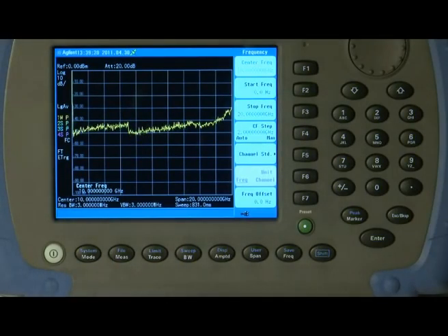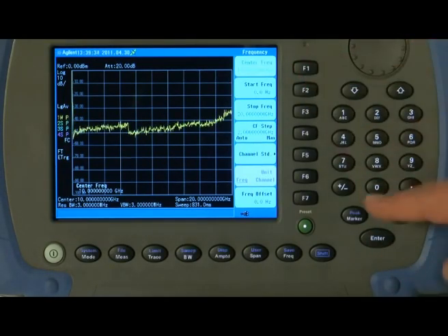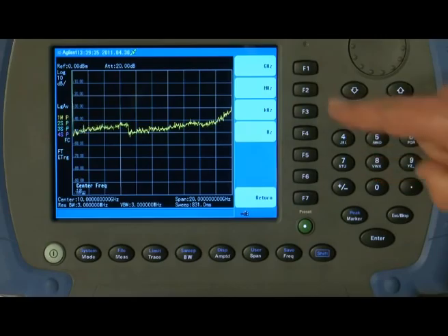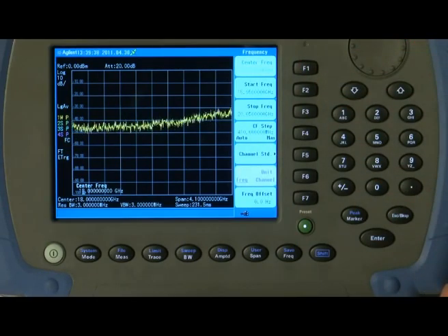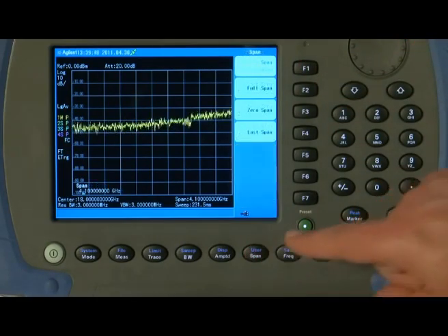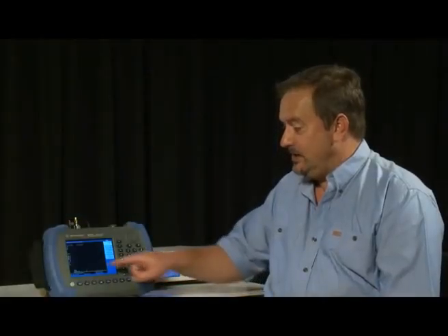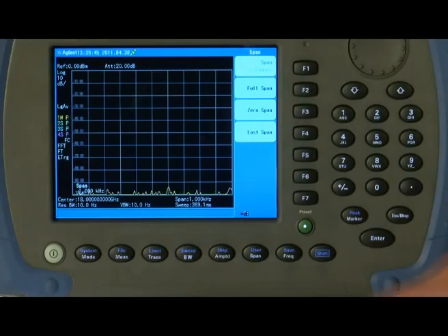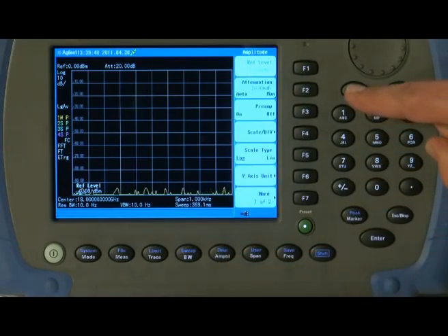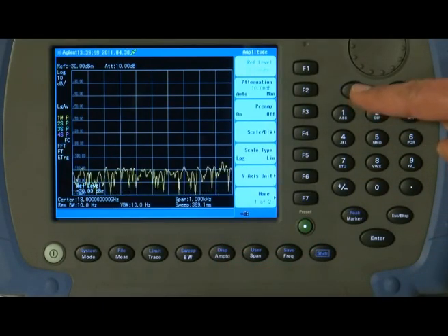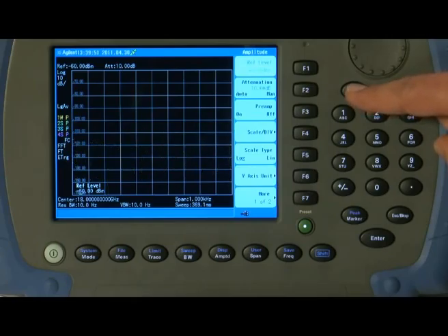And then let's select a typical microwave frequency, let's say 18 GHz. So I'll press center frequency, 18 GHz, and we'll zoom in a bit. So I'll press span, and let's enter a span of, say, 1 kHz. You'll see the traces disappeared off the bottom of the display.